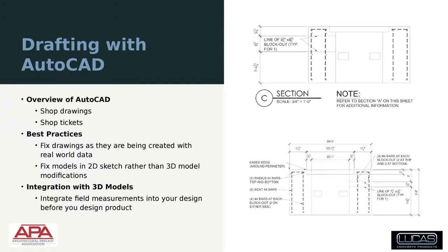And again, your shop drawings that go out to the client, it's fine to integrate some of the 3D modeling to help them see those things, but we really like to slice and dice things in 2D, mainly because you can tie back to things like column lines. You can tie back to sections that go back to the contract drawings. You could still integrate those two things together, but we find that there's a limitation in the 3D modeling drawing profiles, meaning it doesn't do as good a job picking out nodes and sections and details that you need.